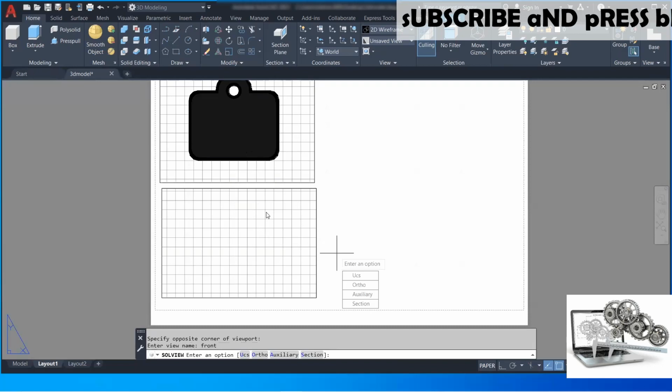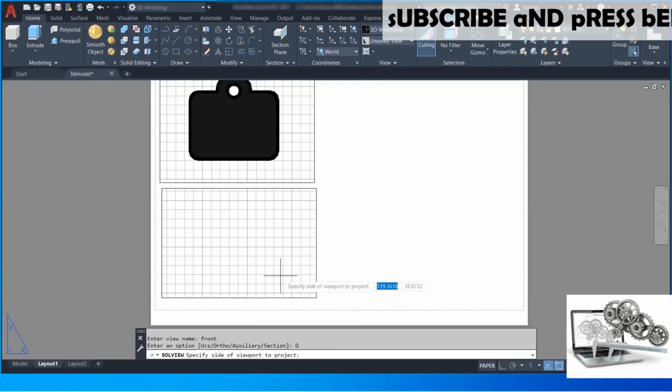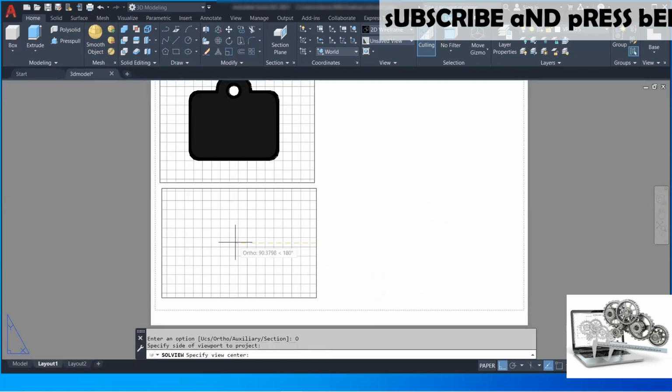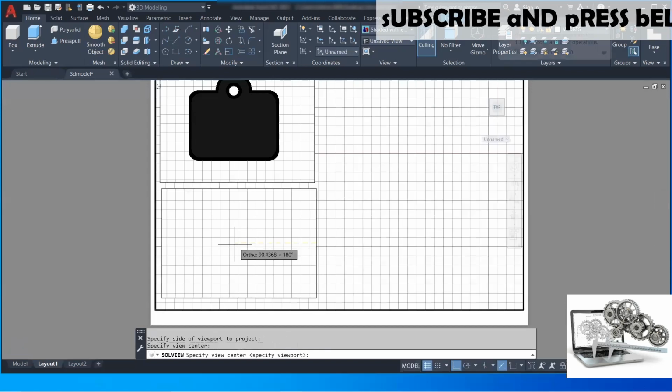Okay, so the cycle goes on repeating. So now I want another side view here. So we are going to generate a side view from this front view. So again we will select ortho, and then we are going to project from the right hand side. Okay, so we'll go with the right hand side viewport, click here and drag your cursor to the left and click. It will generate a right hand side view.